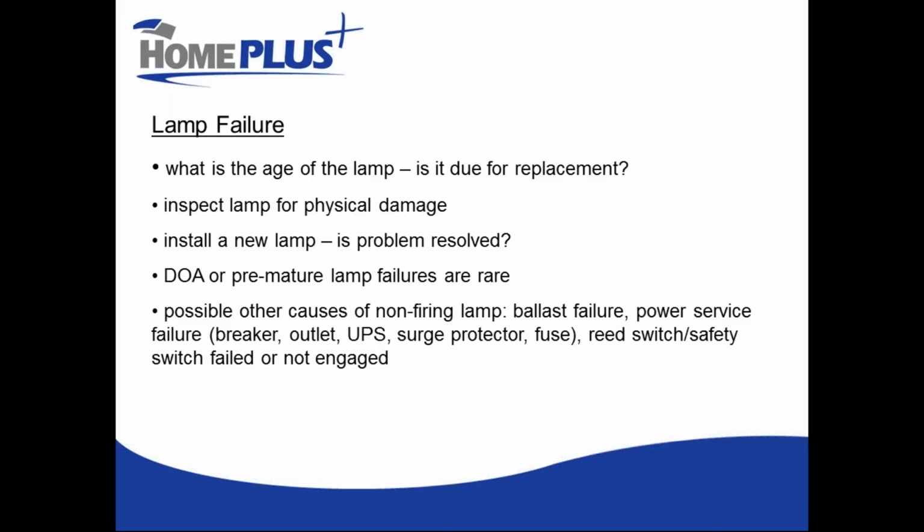Yeah, absolutely. Then he had a question that sort of falls into this: my PHO instructed me to have 2 to 4 ppm free chlorine. Is this way too high? Well, 2 to 4 free chlorine may be necessary if your chlorine contact time is really low.